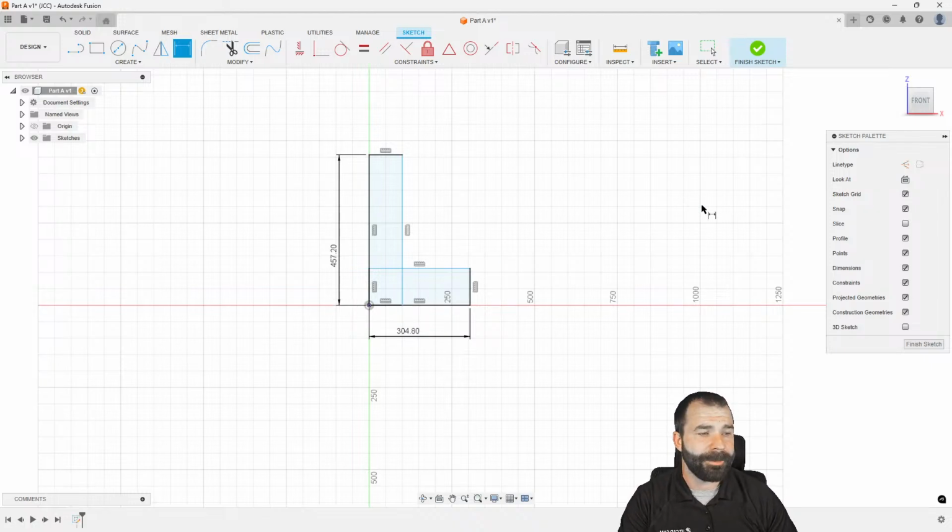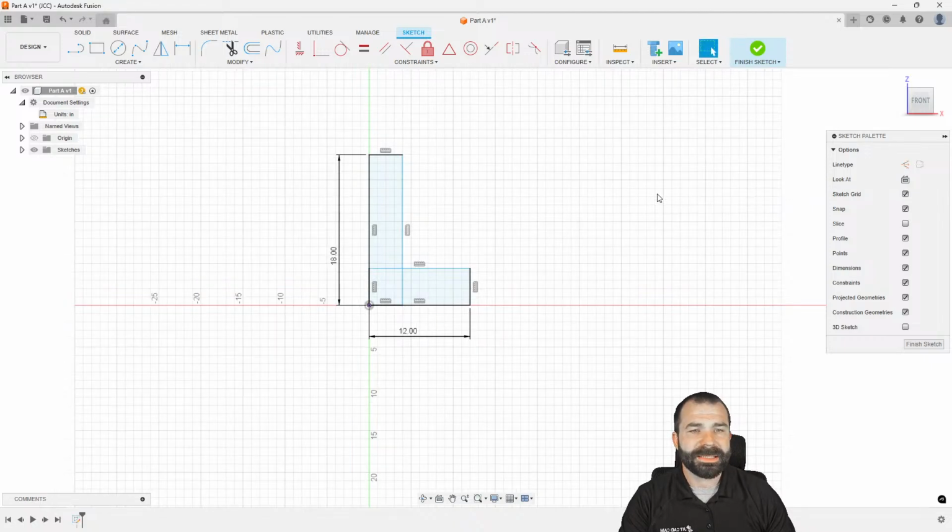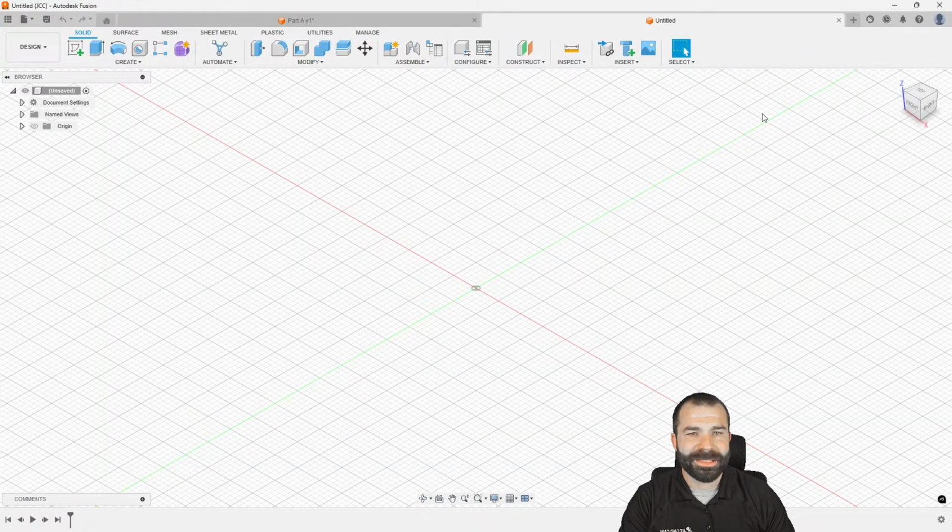even though this entire sketch area is set in millimeters. So one thing I can do is switch my document settings at any time. As you're going to see, I go up here to my document settings, and Unit is now switched to inch. If I would like, I can set that as my user default. So the next time we open a file inside of Fusion 360,